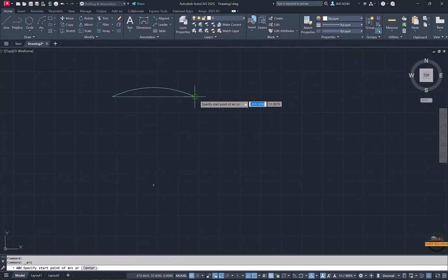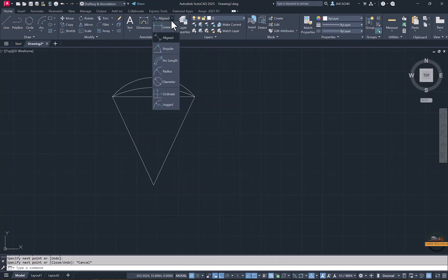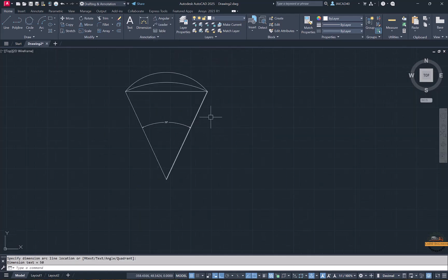If I take a more start angle, I set that to be 100 degrees. We can see that the slope will be changed, so the center will be changed. If you want to check the angles, we can just select the center point of the circle, and we can measure the exact angle that is forming. Like if I want to check this angle, we can just check the angle, 50.